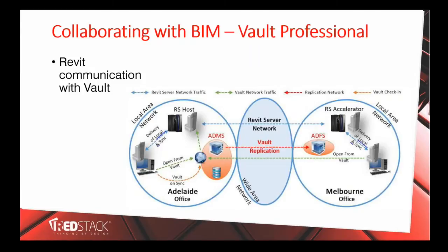There is a central file on the Revit Server networks which manages all syncing to central and element or workset permissions. Once Revit Server is tasked with the work sharing workflow, Vault oversees all other aspects of the Revit project workflow. Revit links are one such function that Vault can manage, in addition to the general models or CAD files from outside consultants. They're also stored in the Vault area as they are received.